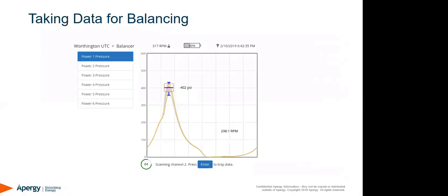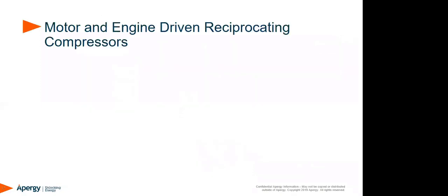You're mainly interested in your peak firing pressure data, so you can adjust the manual valves to keep the engine in equilibrium. This is a screenshot of the actual 6400 screen. While it's taking data, you can see we've got our stat box pulled up there, so we can see our deviations in peak firing pressure as well as our peak firing angles.